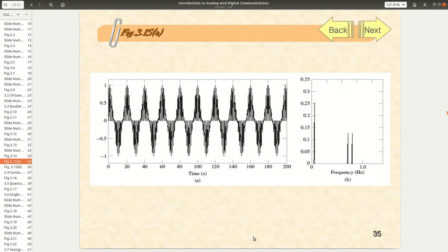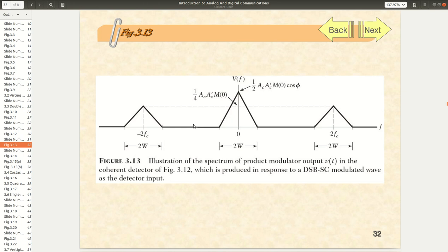Here in my signal, this is the upper sideband, and we name this side the lower. Both of them are symmetric around the origin. So if you send only one part, then you can recover the same information. Instead of sending two parts and wasting two W, I will just send one W, and without the carrier.